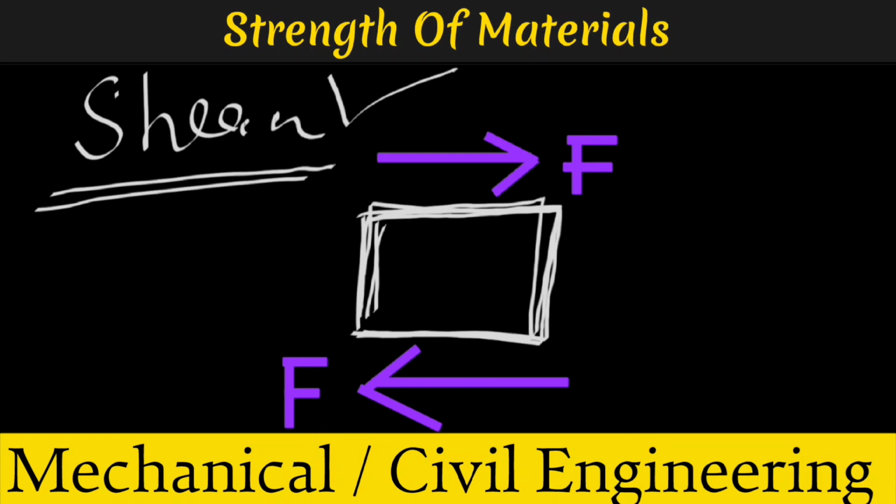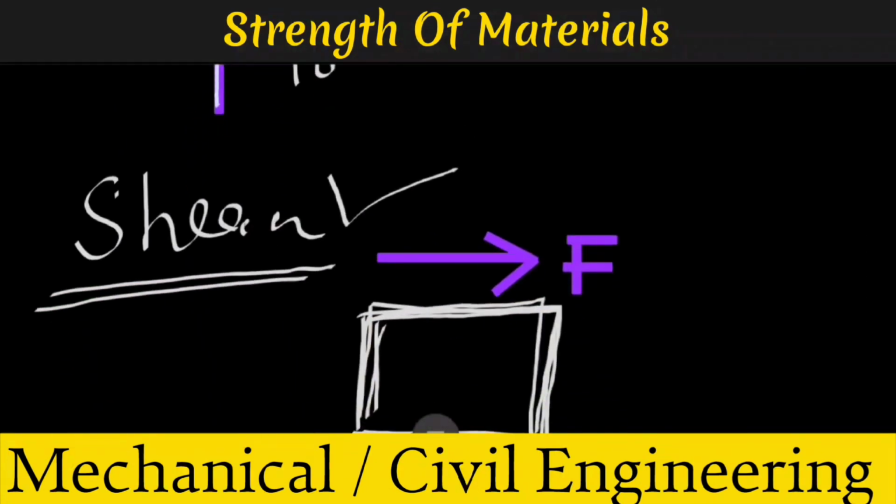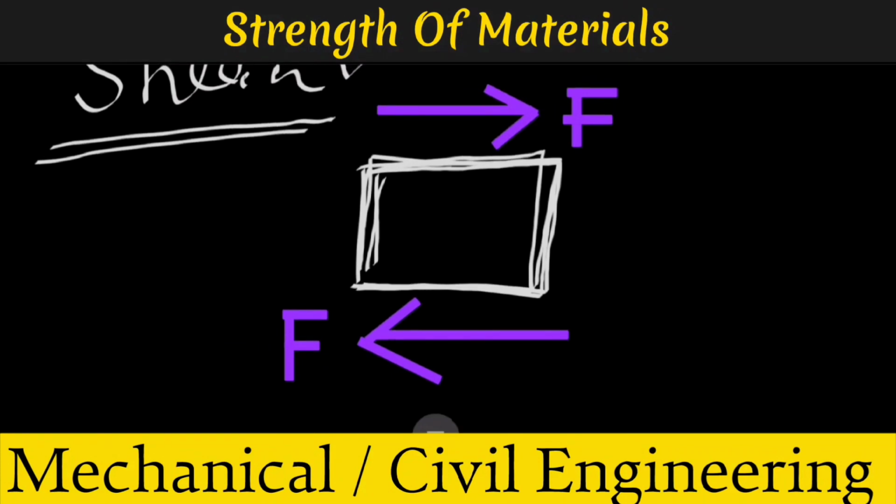Always remember, the force acting perpendicular is what we call the normal load, which is always at 90 degrees to the cross section. Now talking about the shear load, or shear force, when the force acts on a body, this is the body, then the force is parallel in nature.